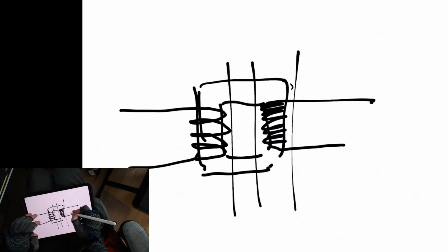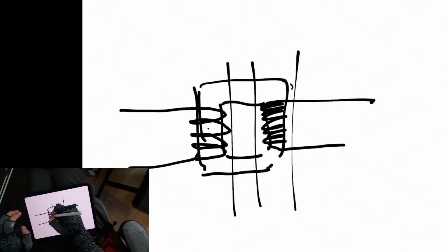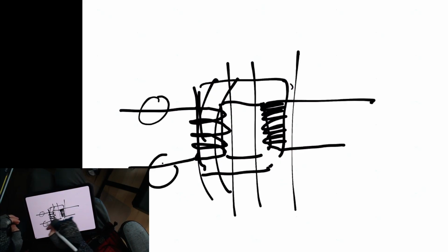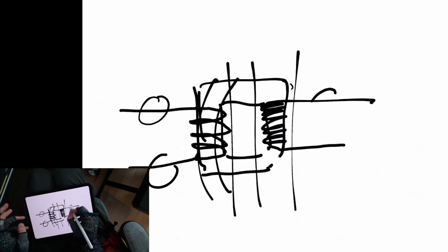I know that you're going to have a magnetic field that expands and contracts, right? And since one side is not charged and the other side is charged, as those magnetic field lines expand, they will pass over these wires. They'll cut over the other coil, and it will induce a current. It will make voltage start flowing on the other side, and it will basically kick back against this other one.